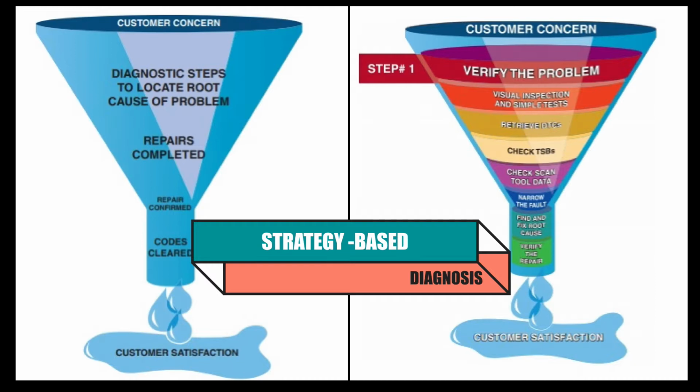A funnel is a way of visualizing a diagnostic procedure. See Figure 1.1. At the wide top are the symptoms of the problem. The funnel narrows as possible causes are eliminated until the root cause is found and corrected at the bottom of the funnel. All problem diagnosis deals with symptoms that could be the result of many different causes. The wide range of possible solutions must be narrowed to the most likely, and these must eventually be further narrowed to the actual cause. The following section describes 8 steps the service technician can take to narrow the possibilities to one cause.